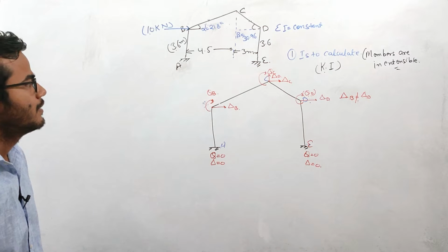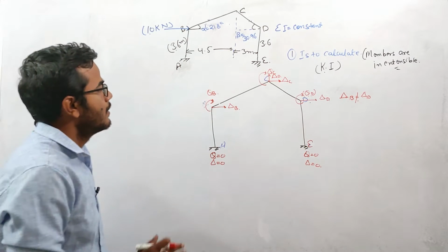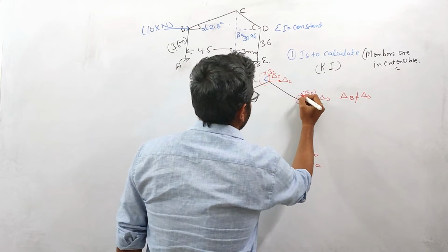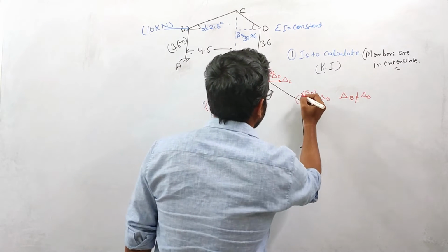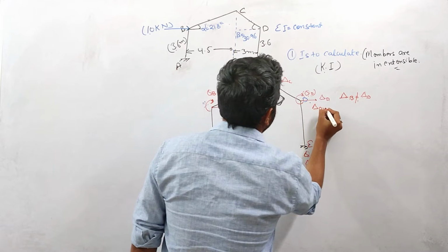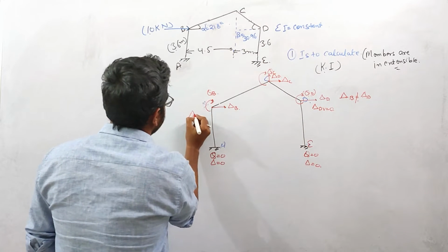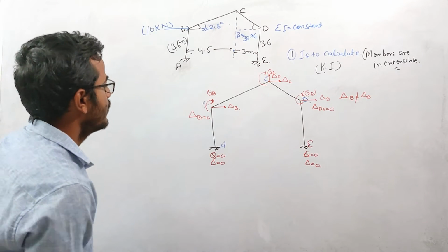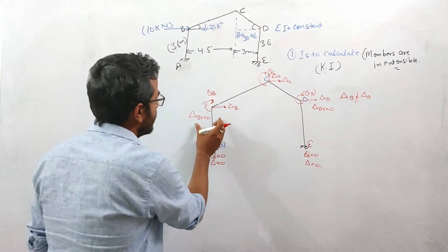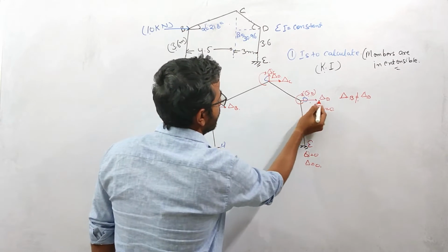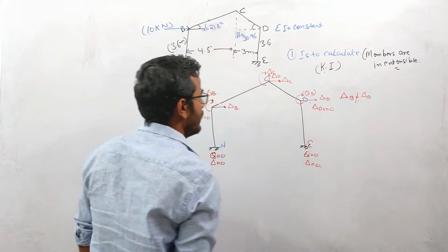Here also the axial deformation is basically 0, right? For this delta D in the vertical direction, delta D vertical is 0 basically. Here delta B vertical is 0. Because these members we are considering as inextensible, this D point will always move perpendicular to this member.